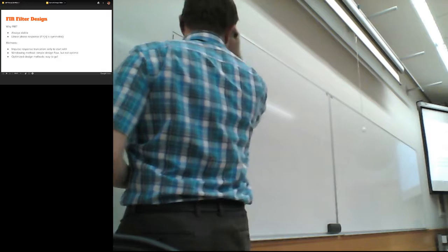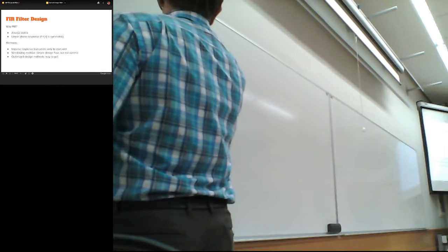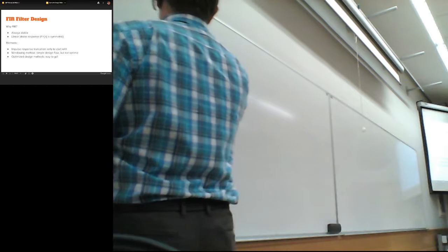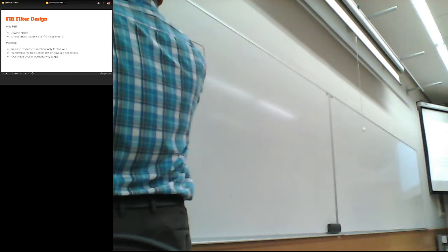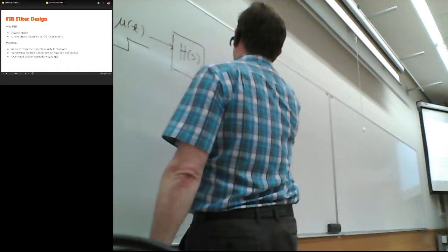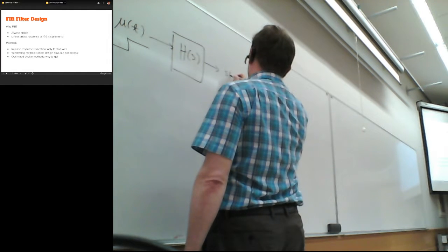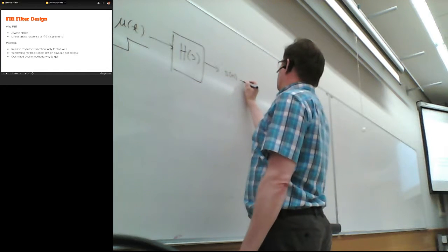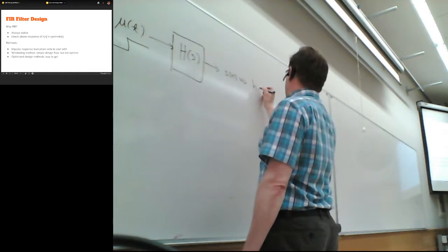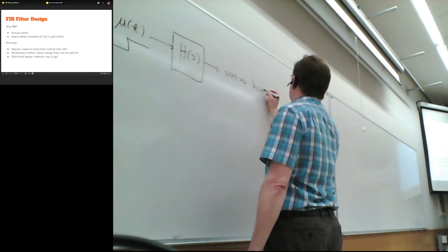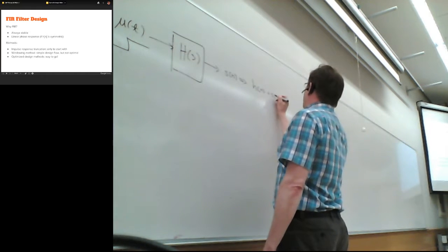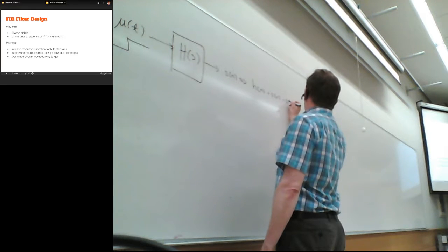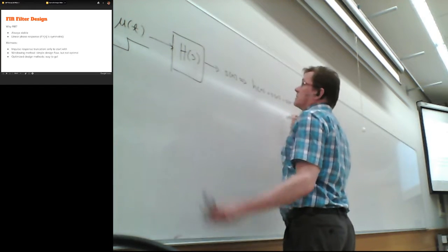or it could be a linear system, or in continuous time, and you then run a step function from a function generator, and what comes out, when you sample it, is the step response, and actually then you get the impulse response from that one, and now you can simulate with some accuracy.